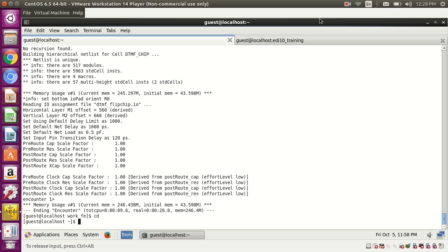During this NLA, NLB, NLC, we'll run through all the PD flow, all the sign off checks, PT, PrimeTime and Redhawk, everything we will do. But we don't run SI there, because we are not that keen at that time. Maybe at NLC, whenever we are freezing our designs, just before we get the full 100%, at that point we will run PTSI, that's it.